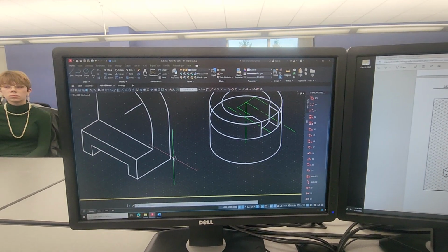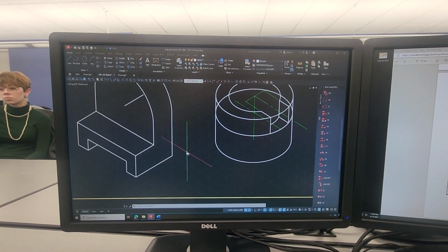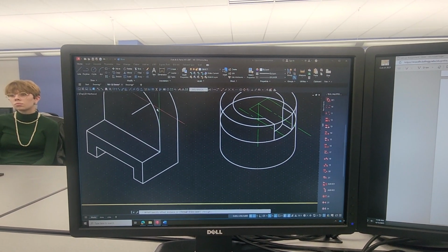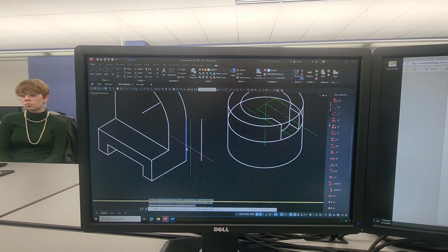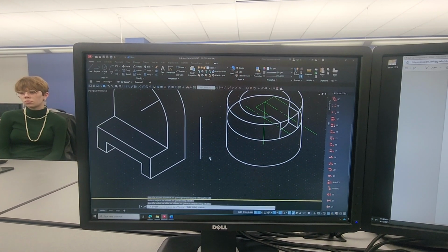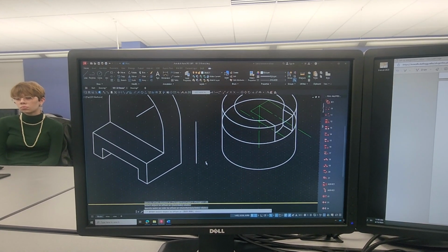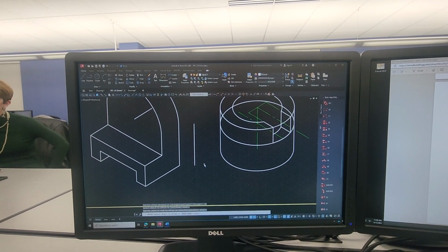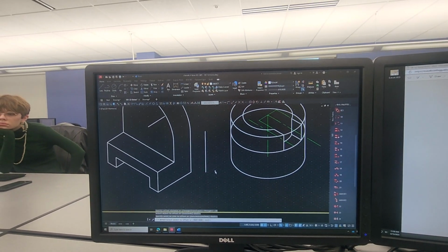So let's say we know the distance from here to the next place I want to go is 3/8 of an inch. If I do an offset, and I know I want to go that 0.38, and I hit enter, if I pick this and go 3/8, it's going to go automatically, horizontally, vertically, whatever direction, always parallel at a given distance. It will not respond at all to your grid. It does exactly what the offset does at a given distance, parallel to what I've got.